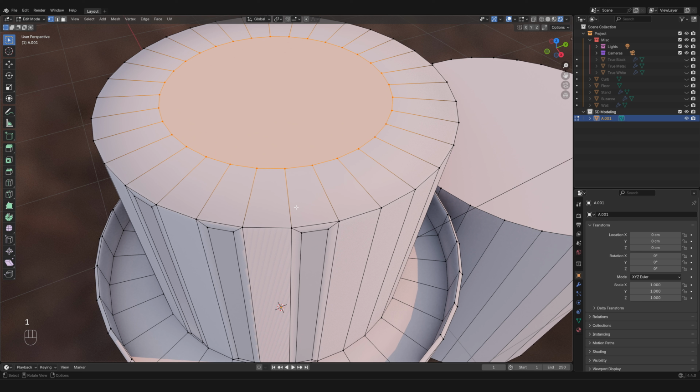Now starting to play a little bit with vertices, I pressed 1 to get into vertices mode, and I could select 2 vertices and press J, not Ctrl+J, just J to join them. And it's gonna link basically the vertices. I can also select multiples, and then it's gonna look at the order in which I selected them, and then it's gonna create for me that connection.